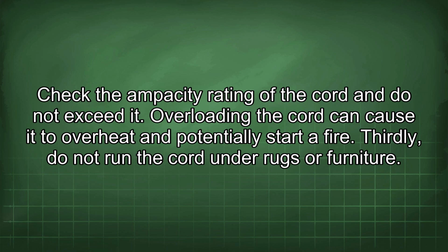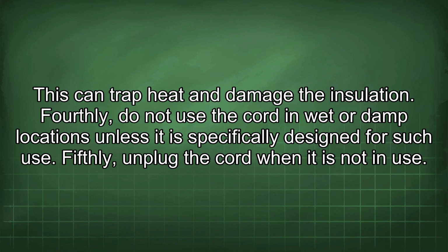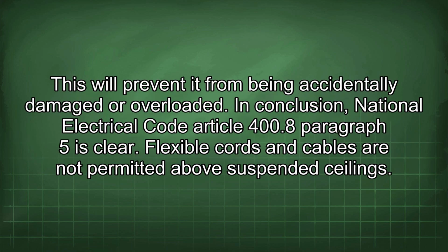Thirdly, do not run the cord under rugs or furniture. This can trap heat and damage the insulation. Fourthly, do not use the cord in wet or damp locations unless it is specifically designed for such use. Fifthly, unplug the cord when it is not in use. This will prevent it from being accidentally damaged or overloaded. In conclusion, National Electrical Code Article 400.8 paragraph 5 is clear.